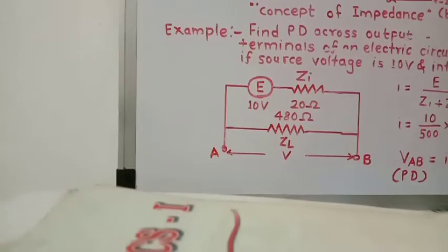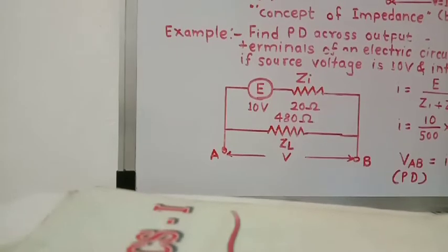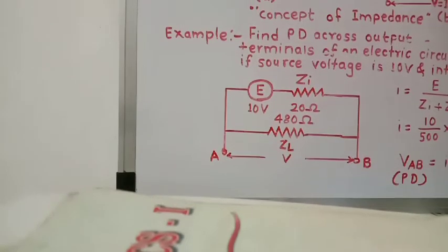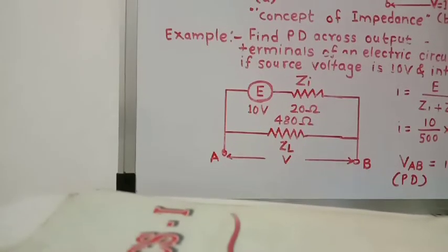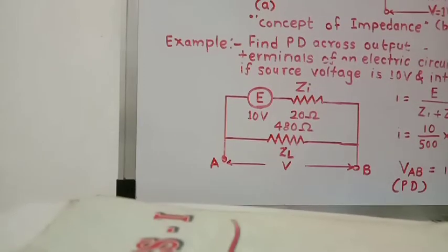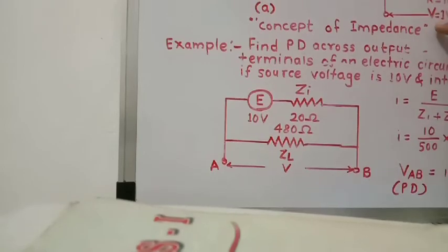Now the voltage across this internal resistance r is equal to I into r, that is I means 0.1 and r means 5 ohm. So 0.1 into 5, that is equal to 0.5 volt. So this 0.5 volt will drop across this r. Okay, now the EMF of a cell is 1.5. So 1.5 minus 0.5, that is 1 volt will drop across this load resistance. So we will get the terminal voltage or potential difference 1 volt.